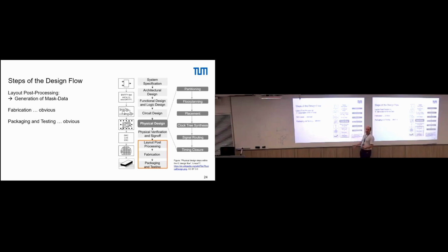Afterwards the chip comes back from the fab, goes to a packager usually, who does the wiring, so the bonding of the chip, packages the chip, and gives you the actual chip with housing back. Then you can test that what you had is still okay. Of course, you can also do some testing on the chip directly, with needle probes and so on, all not so much of interest for us.